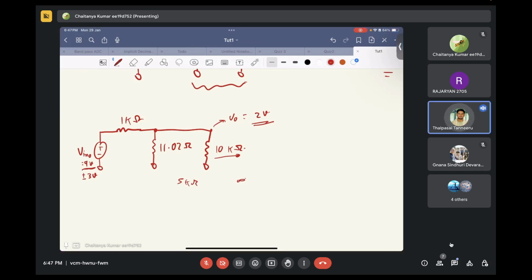Sir, could you repeat again? Yeah. So my question was that does voltage variation cause more impact on the output voltage, or the load variation cause more impact on the output voltage? Voltage variation. Yeah, voltage. Can you explain why? Because sir, the incremental resistance of the diode is 11.02 ohms, which is nearly equal to the increment in load resistance.